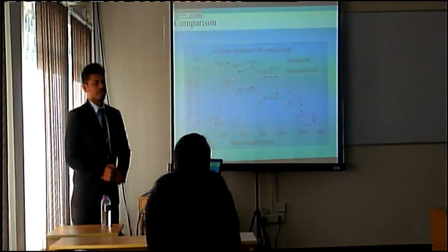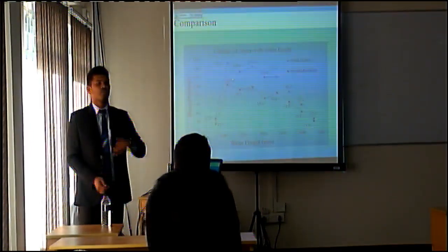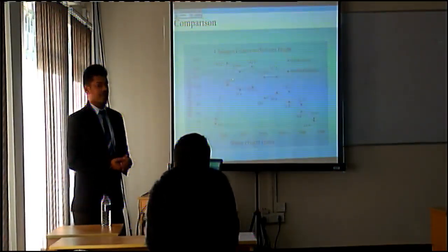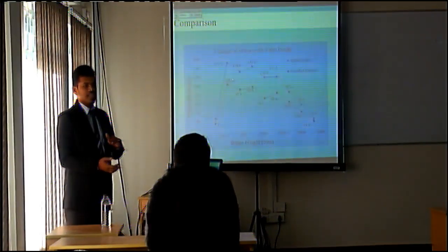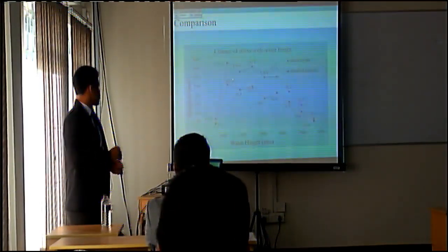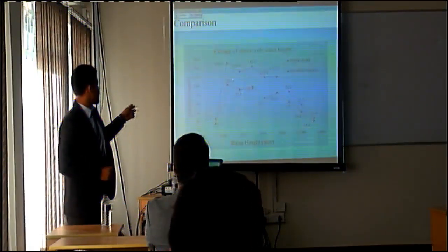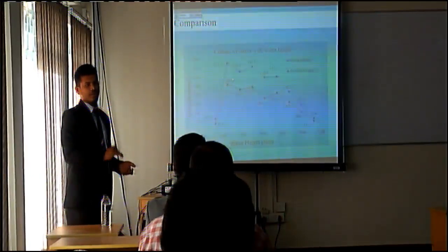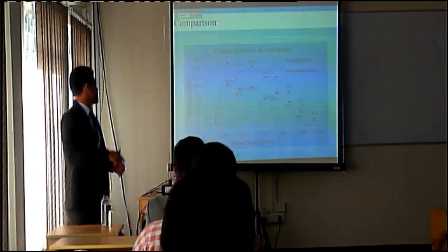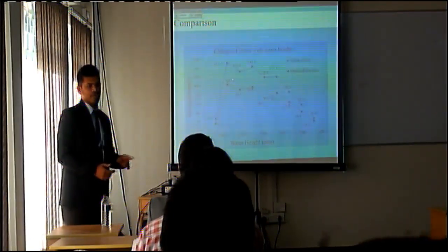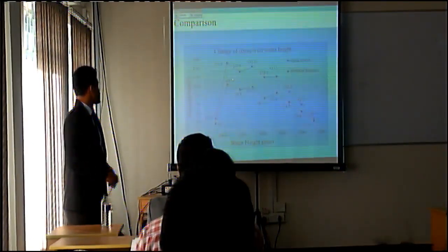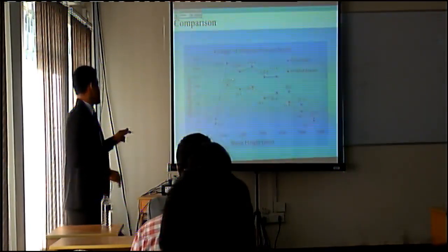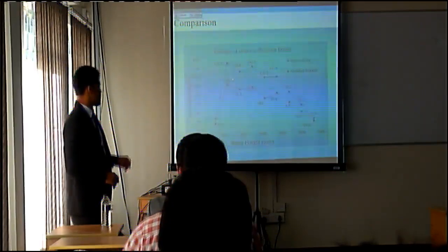This curve shows the change of stress with water height. As this structure has 9 horizontal stiffeners, we have shown the stresses at all the points where horizontal stiffeners join with brackets. The blue curve shows the stresses at the joining points of horizontal stiffeners and brackets in the previous model, and the red is for the modified bracket and modified design. Here you can see that in all connection points, the stress in the modified design is lessened from the previous one.